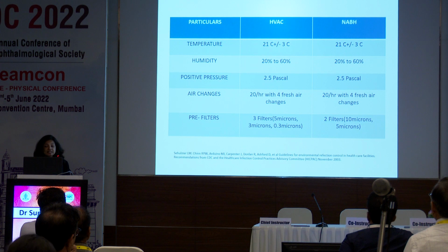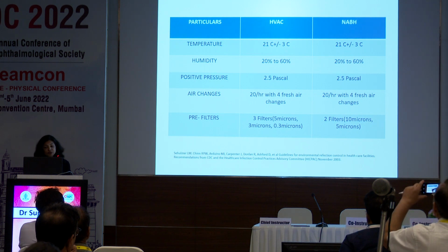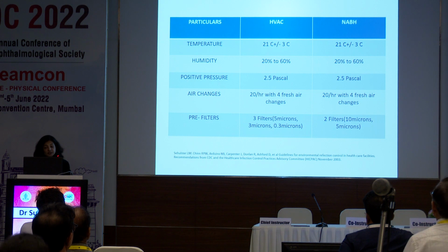As per CDC and NABH, a temperature of 21 degrees centigrade and a humidity of 20% to 60% and a positive pressure of 2.5 pascals must be maintained inside the theater.